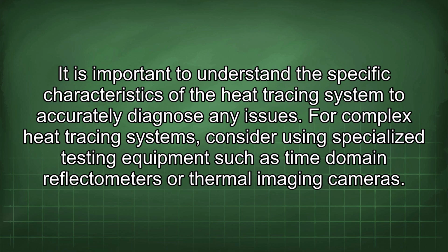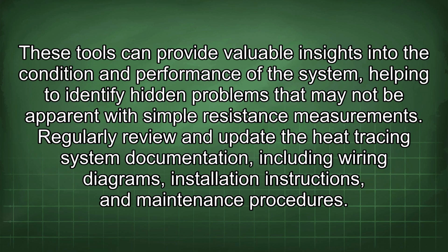For complex heat tracing systems, consider using specialized testing equipment such as time domain reflectometers or thermal imaging cameras. These tools can provide valuable insights into the condition and performance of the system, helping to identify hidden problems that may not be apparent with simple resistance measurements.